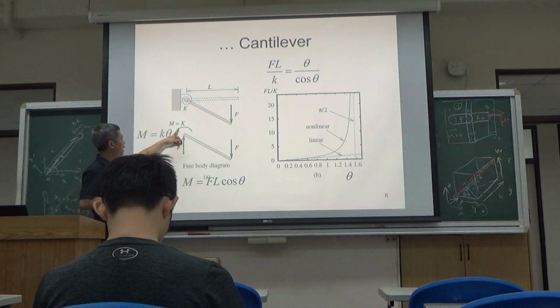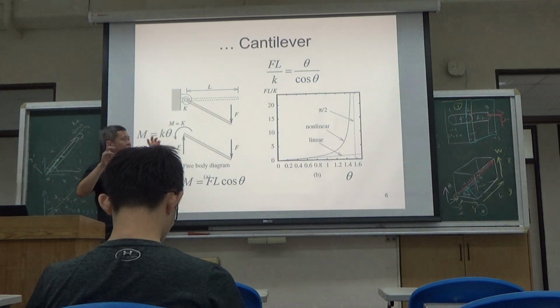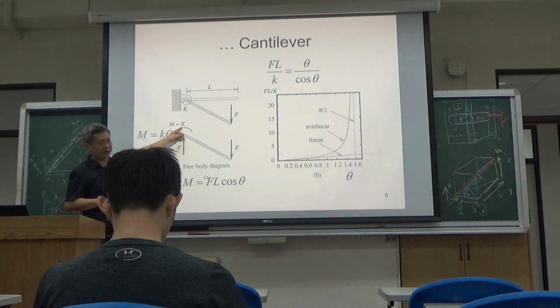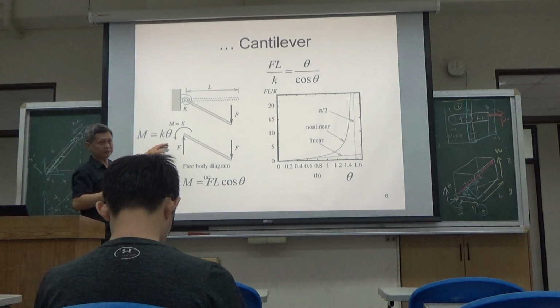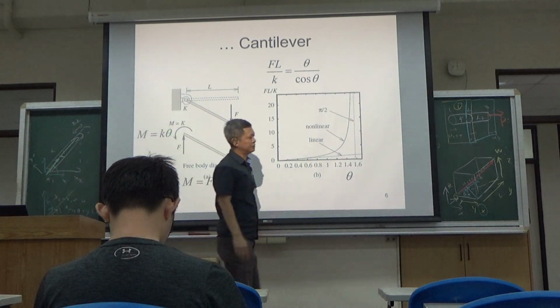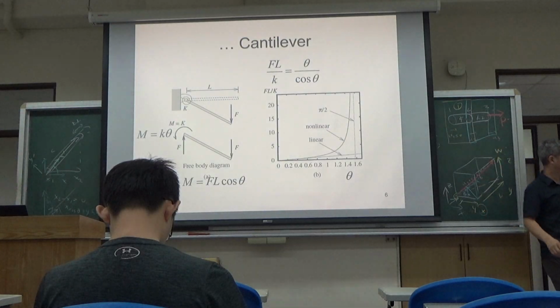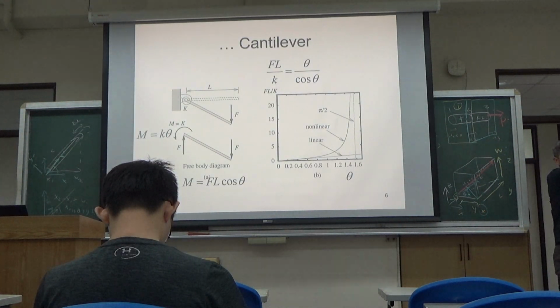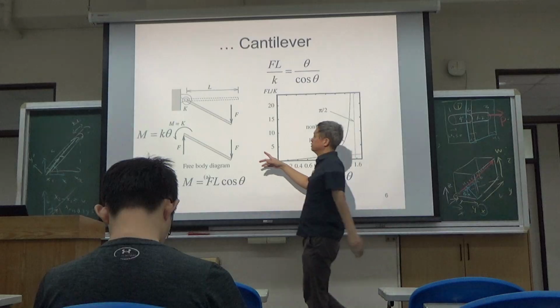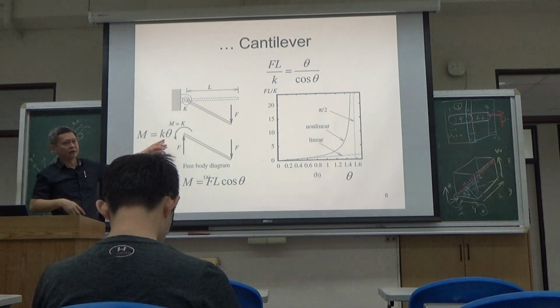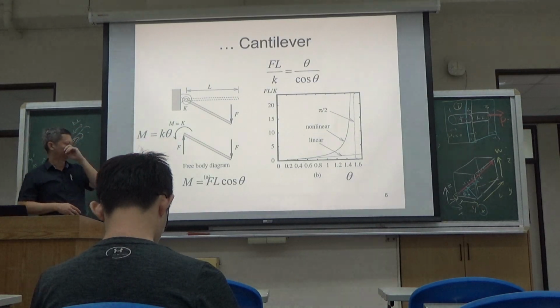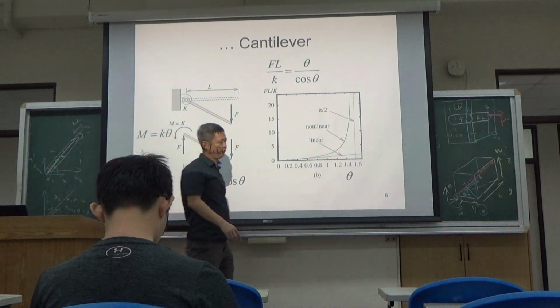So as you bend the rigid bar by angle theta, the torsional spring will provide an opposition moment, which is k theta. So let's imagine this is a rod representing the door. If the door hinge is a spring, then you can have the spring back. So this torsional moment is k theta. The higher the angle of the rotation, the higher the moment.